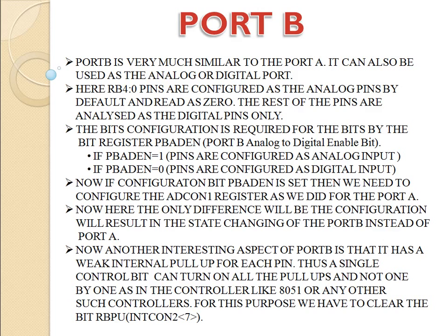Now the most important thing to remember is that if PBADEN is set to 1 while configuring, we need to configure the ADCON1 register as well in the same manner as we did in port A, where this time ADCON1 will apply to port B instead of port A.